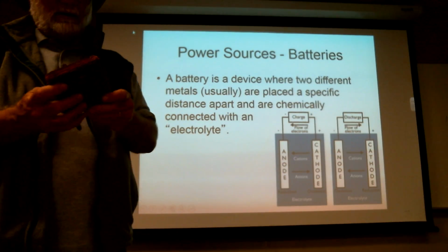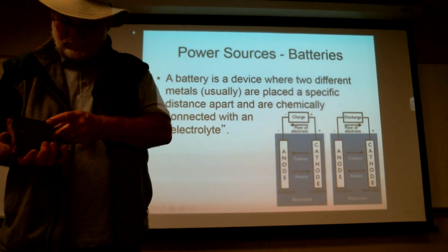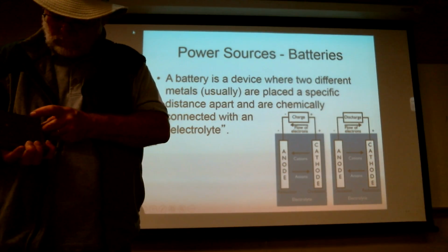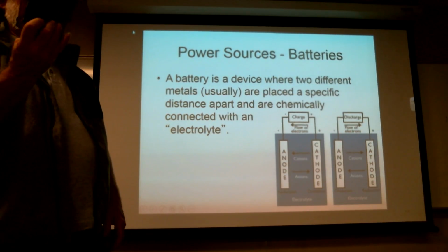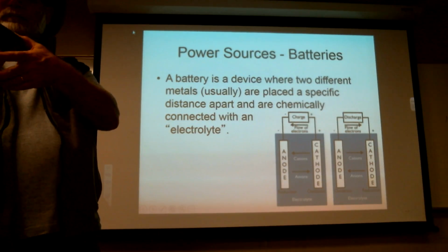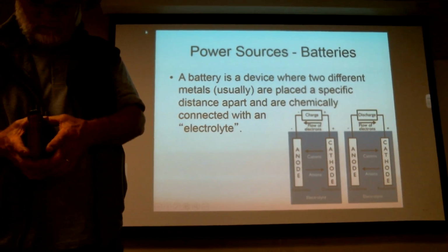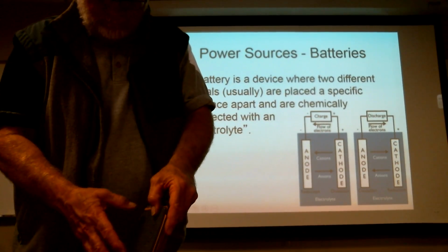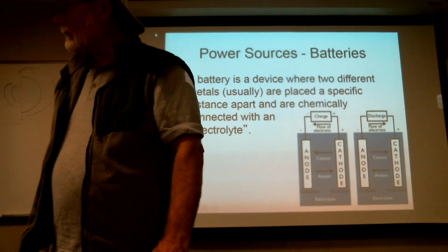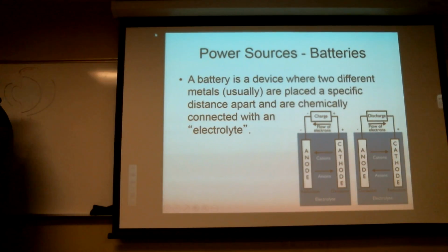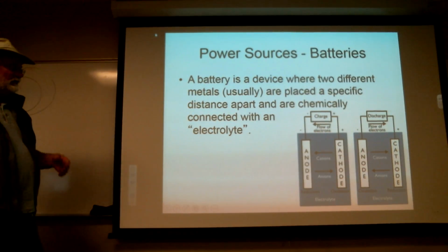So yeah, lead acid battery. We've got plates of lead, and then a little difficult to separate them, but you can see it's slightly different color. That's lead peroxide. See a slight redness to it. Now these are fully charged plates. The other set I've got in here are fully discharged plates. So ultimately, one of these will always be anodic, the other will be cathodic. So there'll be an anode and a cathode.